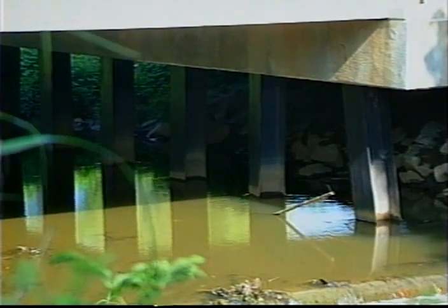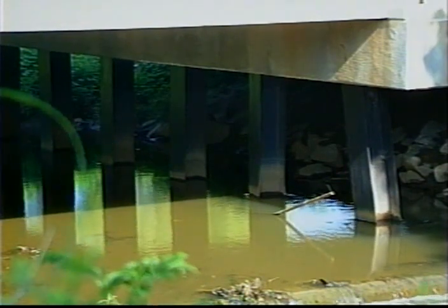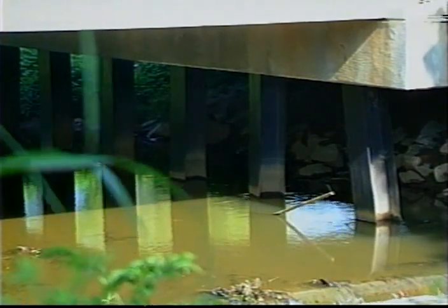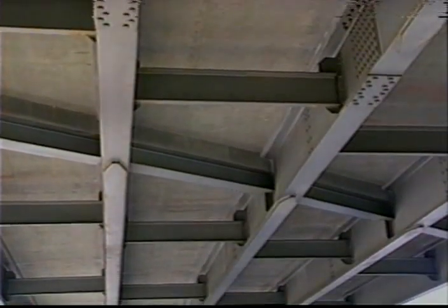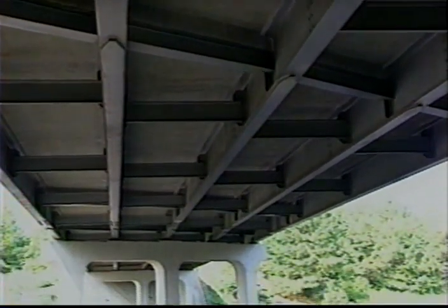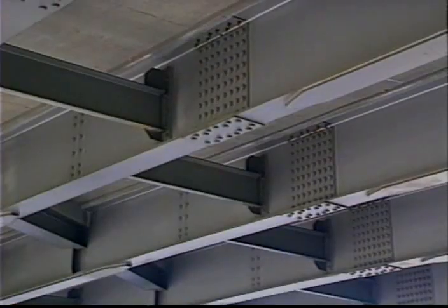Members such as piers, piles, and some truss members primarily support compressive forces. Shear members are subjected to transverse forces or scissor-like forces. Under some circumstances, short-span beams such as pier caps are shear-critical members. Girders, beams, and stringers are primarily bending or flexural members, incurring both tension and compression, as well as shear.